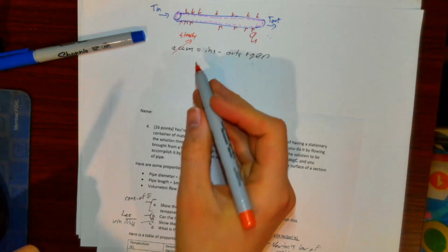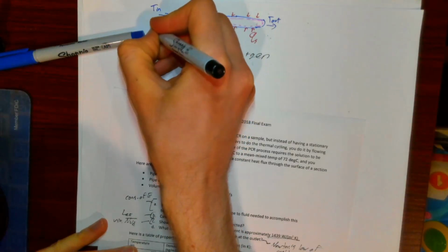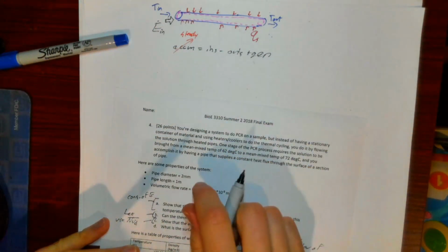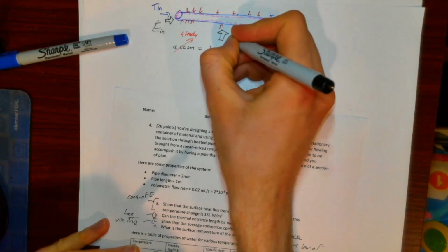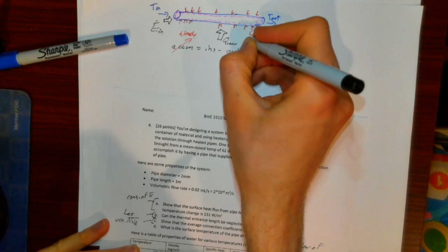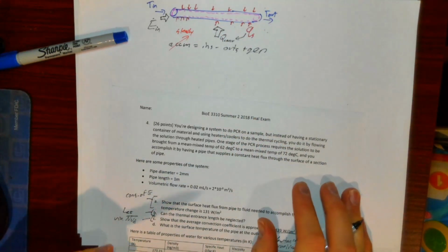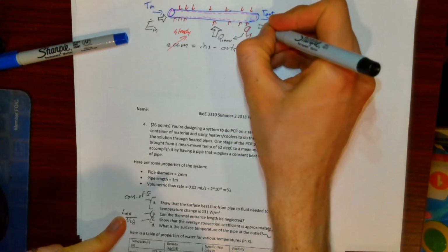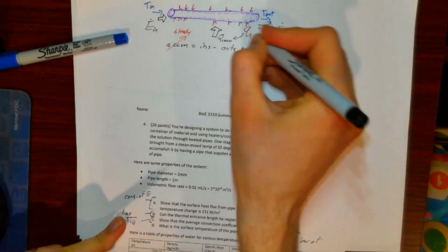If I think about my ins, I essentially have some energy carried by mass going in. I also have an inlet that's the overall Q from this q sub s, and I'm just going to call this Q convection. That is essentially the accumulation of all of this heat flux. All of this heat flux is this heat flow due to convection, and then that's it for my two ins. Then I'm going to have my out, which I'll call E dot out for energy carried by mass out,